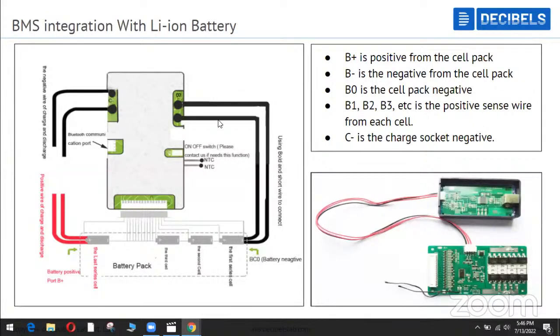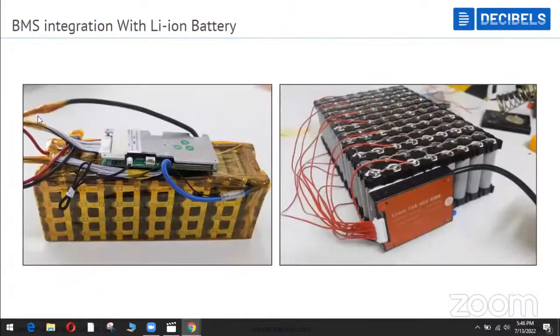So the first part is how the BMS looks on a basic schematics level. So you have a B minus port. That's nothing but battery negative. B minus stands for battery negative, which will be something like this. Yeah, this thick black wire you see, that's a B. Sorry, this thick blue wire you're seeing, right? That's the B minus port, which is going to negative.